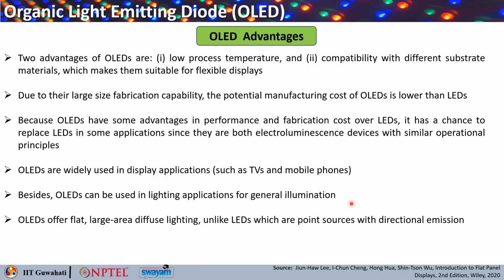Okay. However, OLEDs have some issues, and we will talk about it very briefly, which is called the burn-in issue. So, for a prolonged static image, there is an issue with OLEDs, that there is a ghost-like impression that comes on the screen, and that is why for static images, okay, or for images which are slowly moving, OLEDs are not preferred.